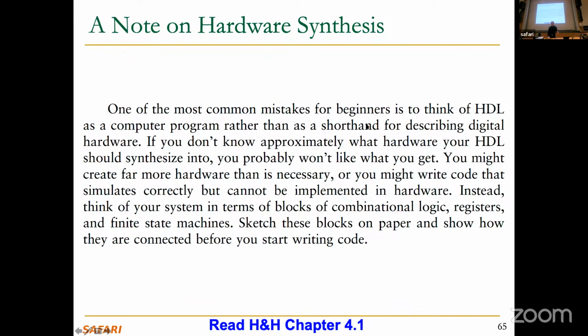One of the most common mistakes for beginners is to think of hardware description language as a computer program rather than a shorthand for describing digital hardware. If you do not know approximately what hardware your HDL should synthesize into, you probably won't like what you get. You might create far more hardware than is necessary, or you might write code that simulates correctly but cannot be implemented in hardware. Instead, think of your system in terms of blocks of combinational logic, registers, and finite state machines. Sketch these blocks on paper and show how they're connected before you start writing code.